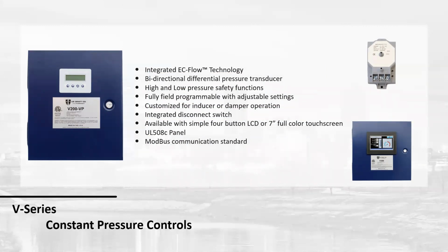The other thing that allows us to do is it gives us a high and low pressure system. If you're reading negative pressure and you don't have a high pressure alarm, that is your first point that you'll know that there's something wrong with your fan. If you don't have a high pressure alarm and your fan dies, you have to wait for that pressure to build up in the boiler itself and have that block flue switch pop. So we'll actually see that at our sensor where, hey, we're outside of our range. We need to go into alarm and lock the boilers up.